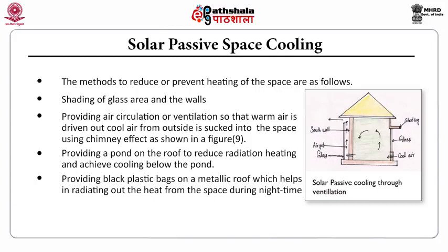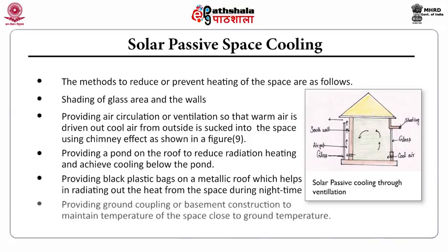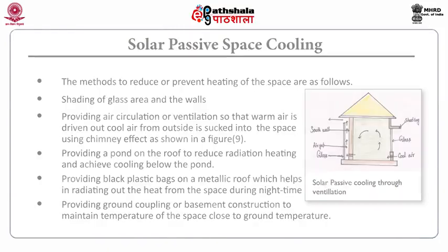Providing black plastic bags on a metallic roof helps in radiating out the heat from the space during night time. Providing ground coupling or basement construction maintains the temperature of the space close to ground temperature.